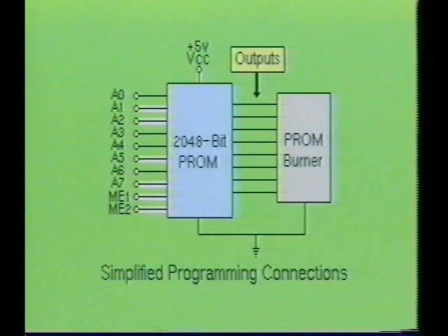Third, apply a logic 1 to either or both of the enable inputs. In this example, we applied a high at both enable inputs. Fourth, apply the high energy programming pulse to the outputs where the low bit levels are desired. Next, advance to the next output and or word, programming only one bit at a time. This sequence is continued until the entire PROM device has been programmed.